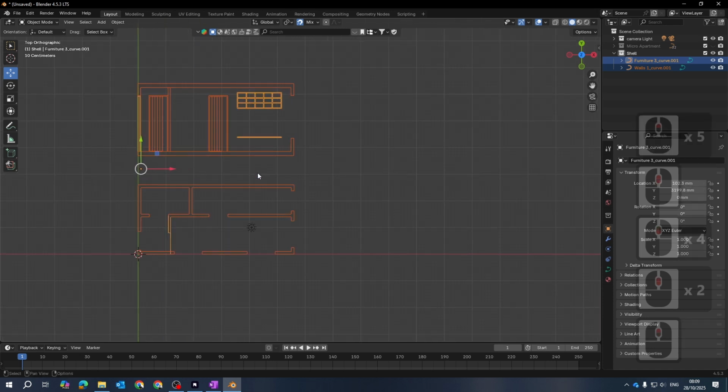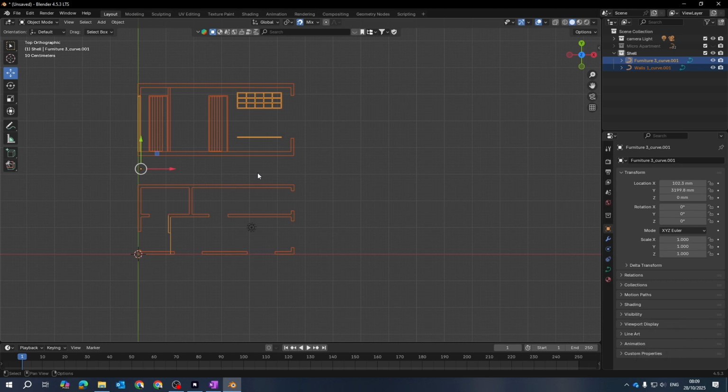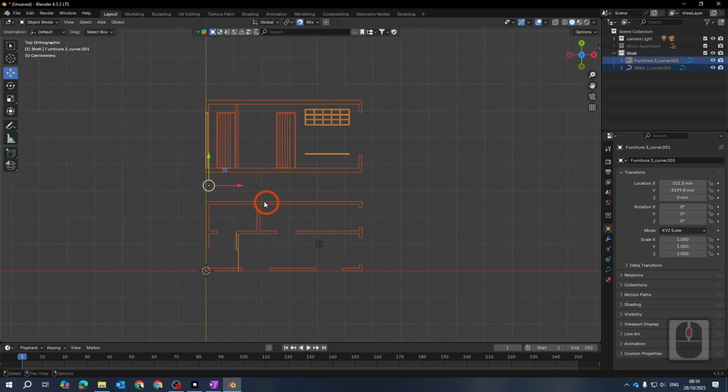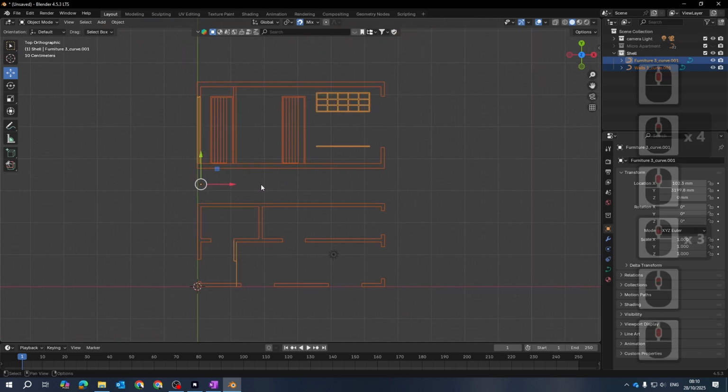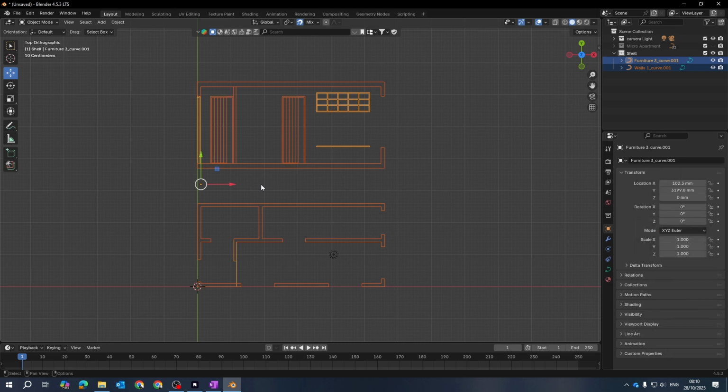The big difference between Blender and something like SketchUp or Revit is that Blender's a clay modeling tool. So it's a free modeling tool. It uses vertices and edges, whereas other software like Revit and ArchiCAD and Rhino are all using maths to put a model together. Yes, you are driving things by shape to a degree, but there's a lot of maths involved, where this is a total opposite. This is more like a sculpting tool. If you're going to sculpt with clay, you can work very accurately in Blender, but it's a different workflow. Blender is more of a free modeling tool, and I think this is a great tool if you're just planning a building and pre-design. You're not being accurate yet, you're just putting a concept together quickly. This is where the software shines.